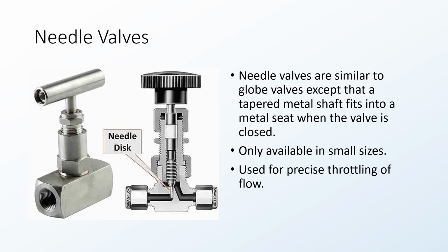If you don't have a way of throttling that flow onto the cover of your gate valve, that globe valve will never open because too much water would be allowed to flow onto the cover. So installing some type of needle valve there will allow you to control the amount of water that goes on. That way, when you need water to come off of a cover, you're not concerned that too much water would get onto the cover.